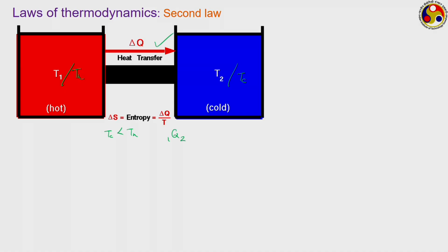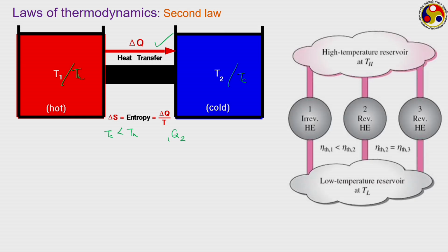We do not need to talk about the concept of entropy here, but something else that we can add here is the corollaries of the second law. There are several corollaries possible from the second law, but we are interested in only two of them, which are more popularly known as the Carnot principles. There are two Carnot principles. In both the cases we are concerned about one high temperature reservoir and another low temperature reservoir. So, here the high temperature reservoir is given a temperature Th, the low temperature one is given a temperature Tl.